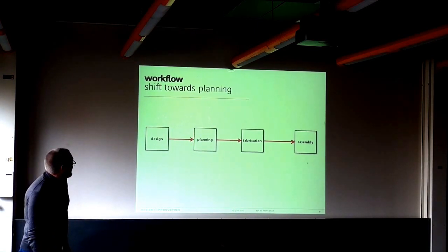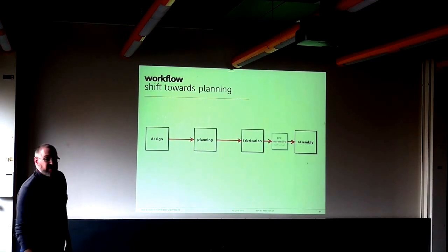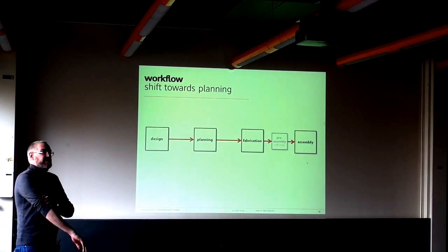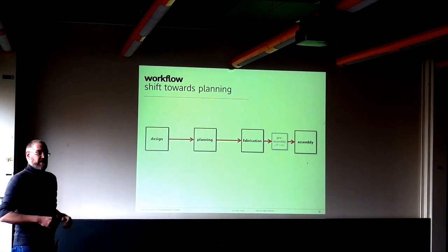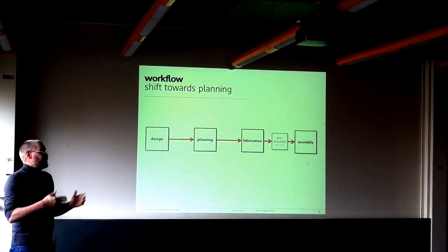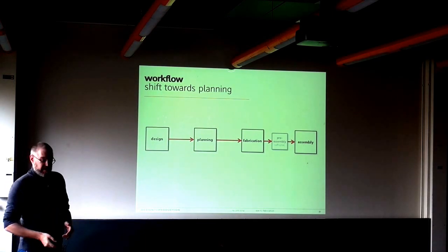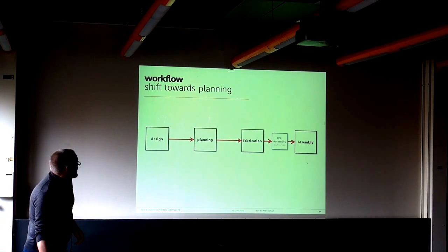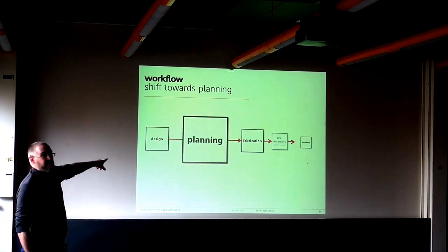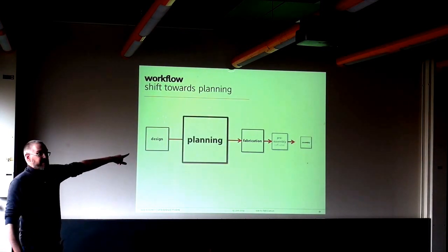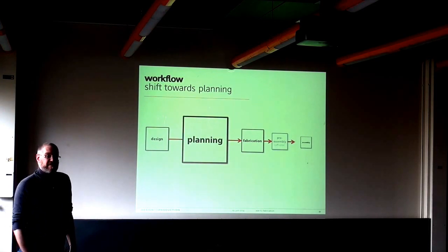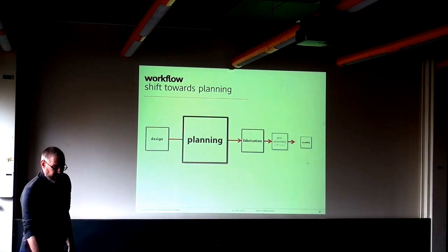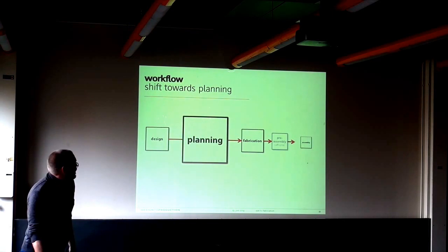And sometimes there's even a pre-assembly off-site, like in the Norwegian project, where you have large chunks of the building, 50 square meter chunks of the facade, pre-assembled off-site and then shipped to the site and put together there. Which means actually you have a lot more planning in the process and a lot less assembly on site.